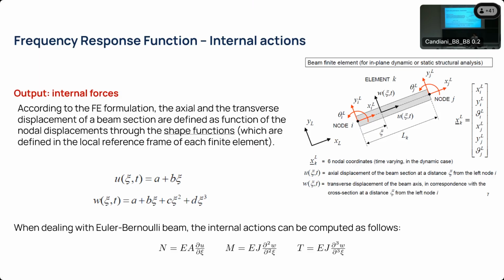So this again is a chain of thought. We solve the problem, find the values of the free coordinates, then use them to compute the parameters A, B, C, and D of the shape functions of your beams. We use those values, and the derivatives of the shape functions of the beam, to express the interactions, and then we get back what we were looking for.